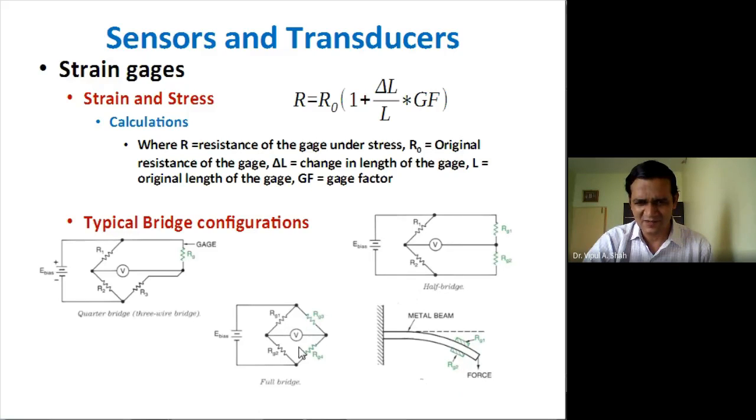Now this particular arm, in this figure, is an arm of your Wheatstone bridge. One of these arms you can have as a strain gauge. Whatever stress or strain you apply on that strain gauge material causes a change in the effective resistance here. The overall change in effective resistance will convert into an effective voltage as an output. Again, here you need a voltage source. So it is a passive circuit in which you are utilizing the strain gauge as a material of construction.